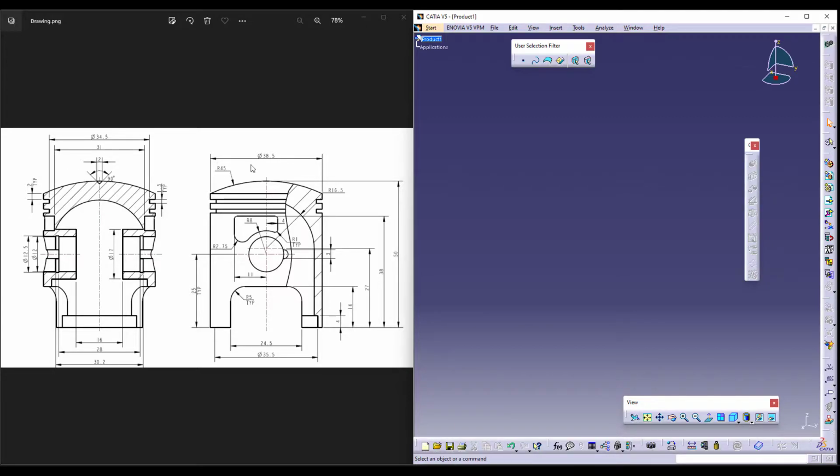One is the front view, which is cut exactly at the center, but only some portion of the section view is shown to you. This is called a local section view, where not the complete view requires a section, but only a certain area requires a section to get a better understanding of the internal cuts. These are the internal cuts which require our understanding.